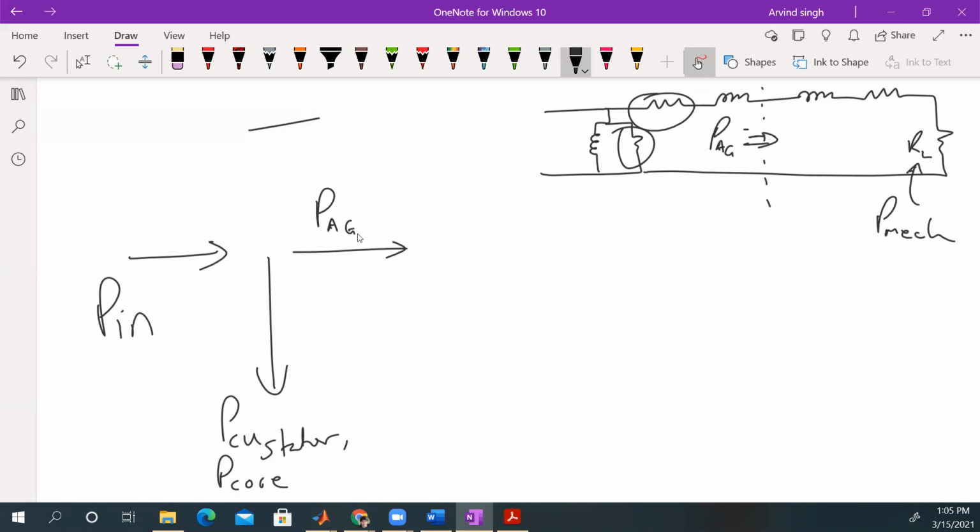So remember the construction of the motor. We have a stator on the outside cylinder, and then you have the rotor on the inside. Separating these two things has to be a gap, otherwise the thing can't turn, right? You just have a transformer. So it goes through that air gap and now it gets into the rotor.